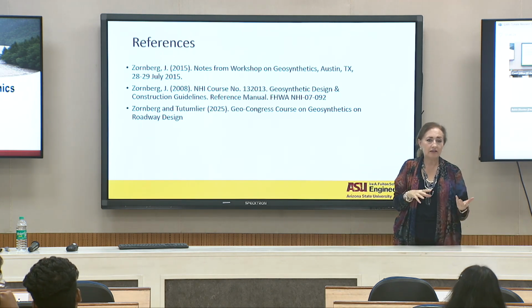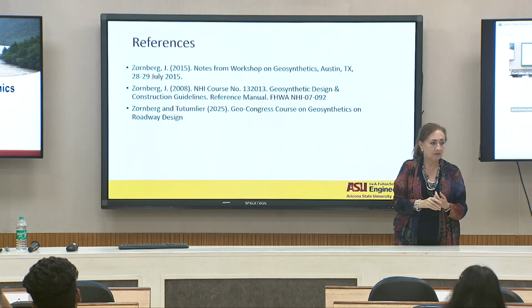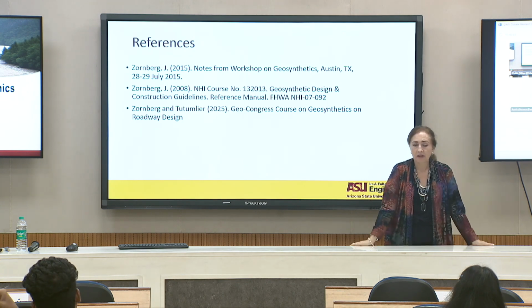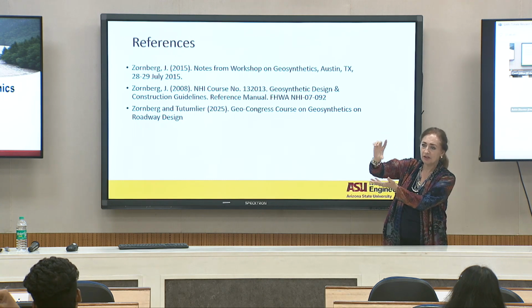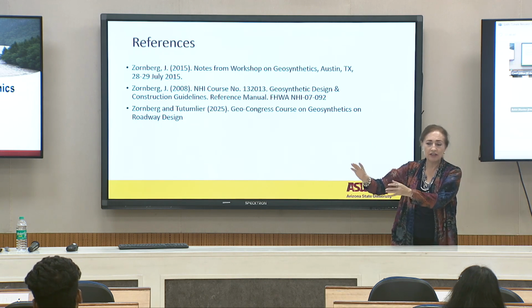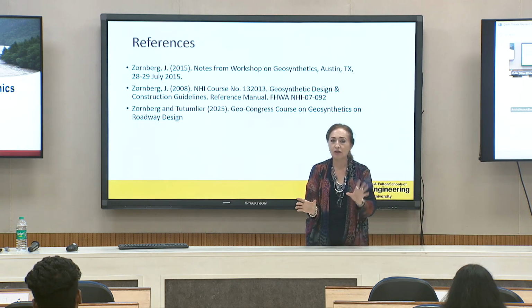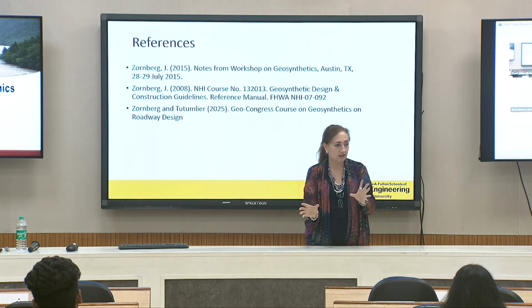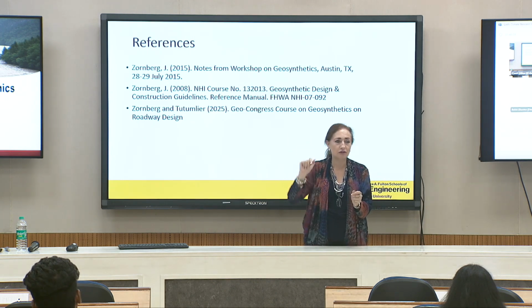Well, if you look behind these things, some of them are mechanistic, but some of them are very empirical. Not only that, they change your asphalt, how much asphalt and granular base, all of this, when you put in the geosynthetic or go without it, and you give them the comparison of the prices below. What does it cost you to put more gravel or asphalt in here? What does it cost you to put one geogrid or two geogrid layers or something like that?